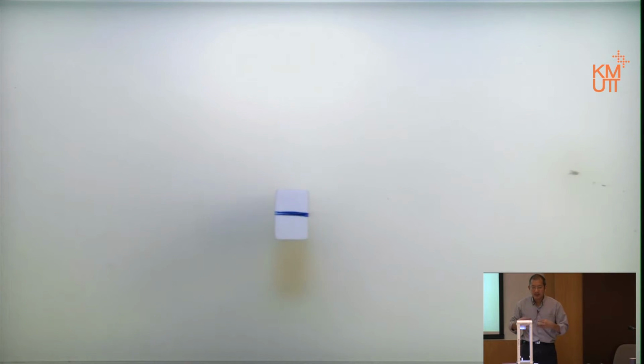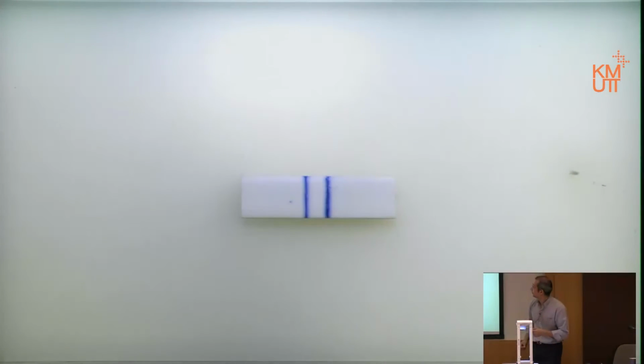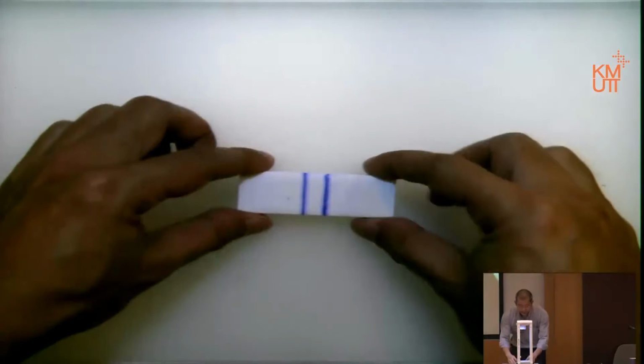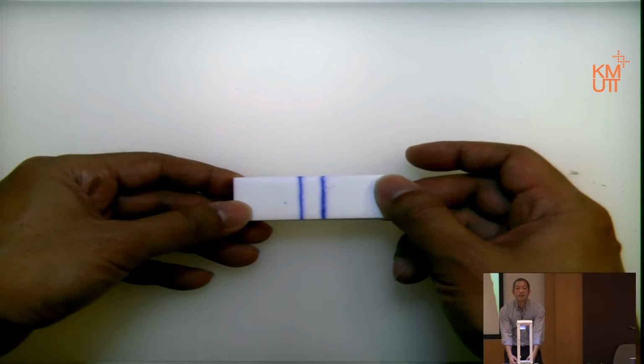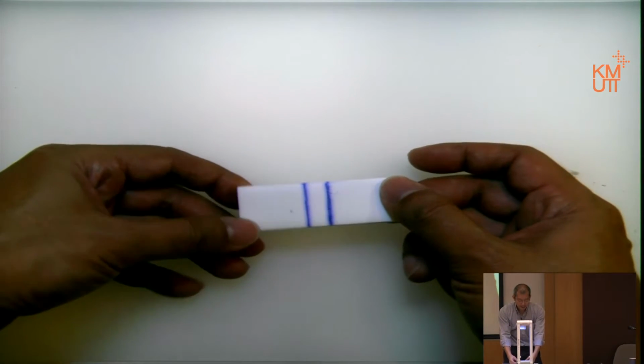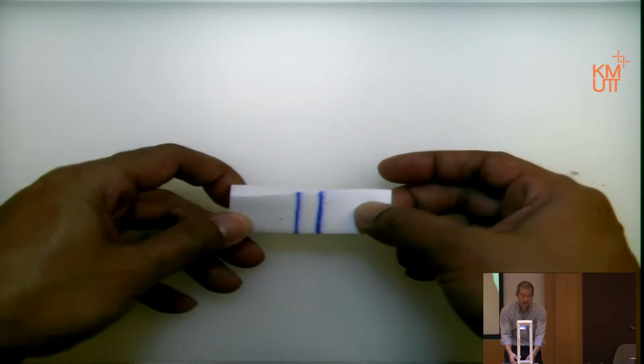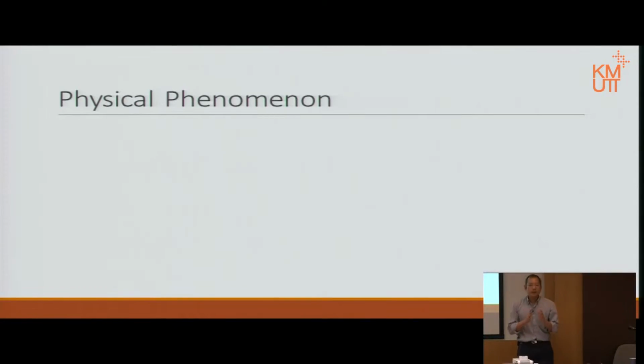Now because we are not using the rubber anymore, I would like you to focus a little bit on my hands. Okay, back to the rubber a little bit. Notice the rubber, when I twist it, these two lines, similar to when we did the bending moment and the shear force, represent cross sections. If this line is one cross section and this line is one cross section, notice that when we twist it, if it's not connecting, it's just touching, the cross section will rotate this way, right? Notice the way the cross section moves is actually sliding on one another.